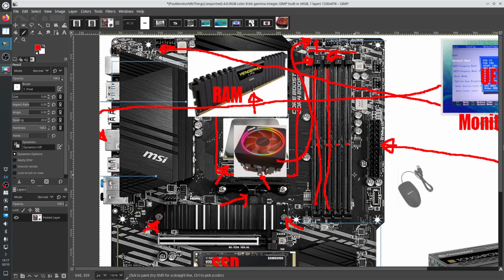Okay. If you don't put a CPU fan, a CPU cooling solution, the CPU will get hotter and hotter, will get to 50 degrees Celsius, then it will get hotter and hotter, it will get to 90 degrees Celsius, which is really much for a CPU, and then it will start to throttle.